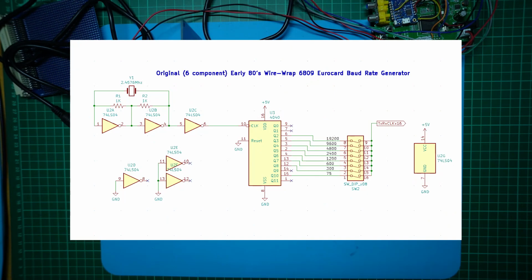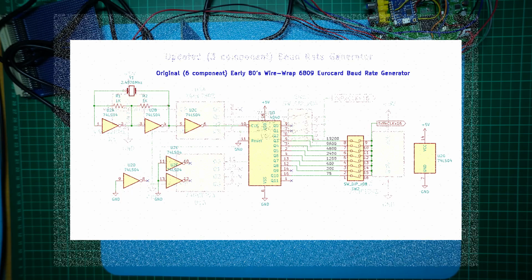Here is the circuit, which, as I've no longer got my circuit diagram, I've recreated by reverse engineering my original YRAP board. These commonly available components, together with different crystal frequencies, were typical for a baud rate generation circuit of the early 80s. For my updated I/O card, I want a simplified and cleaner design, and perhaps also just make do with 4 baud rate options instead of the 8 that I originally provided.